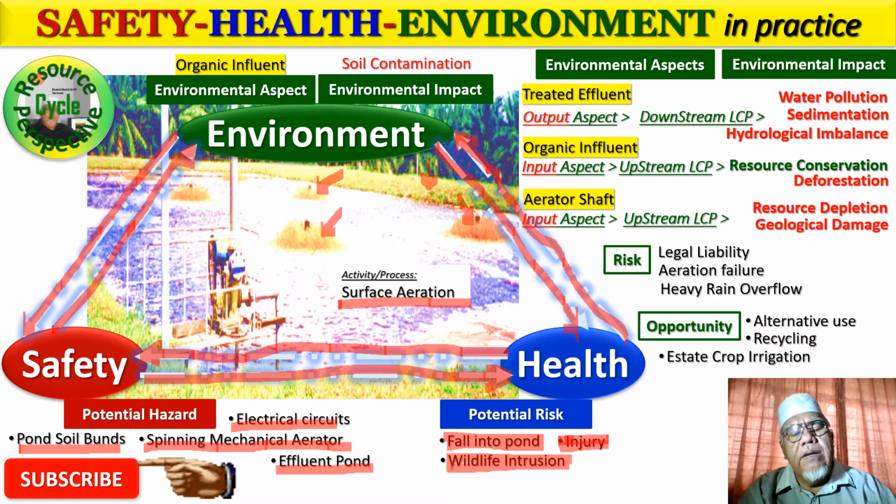And normally for a palm oil mill ponding system, they would achieve, after treatment, a discharging effluent quality around 50 to 100 milligram per liter of BOD. BOD is biological oxygen demand, and the COD might be around 200, 250 milligram per liter. Suspended solids around the region of 100 to about 300 milligram per liter. It's just by experience.